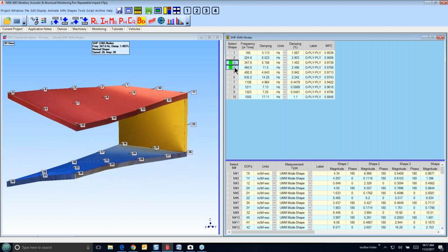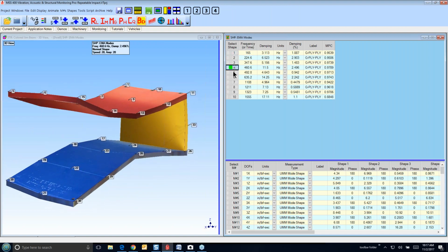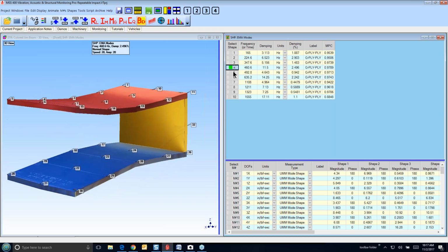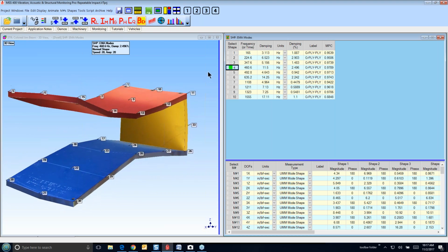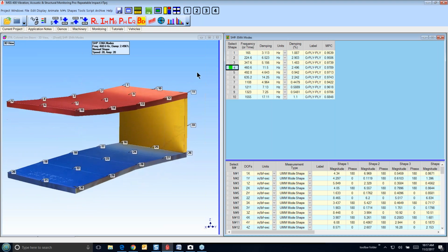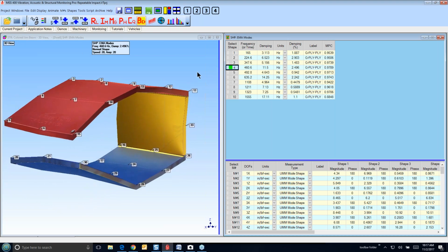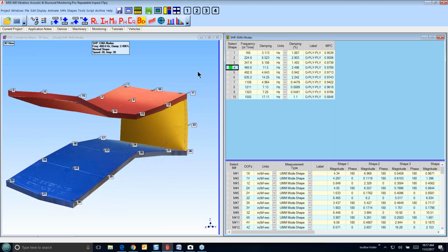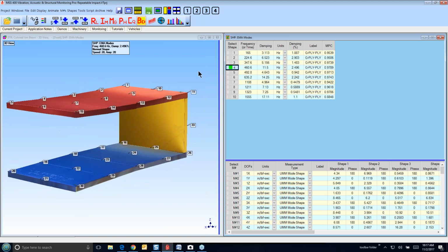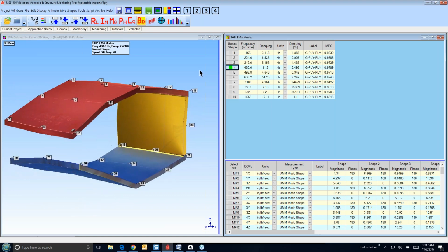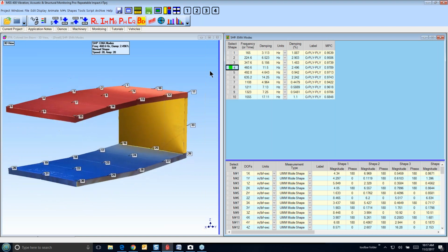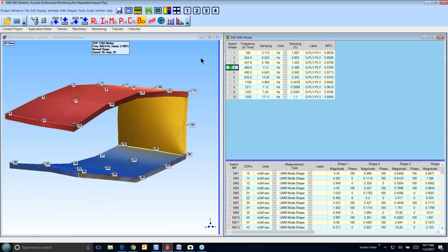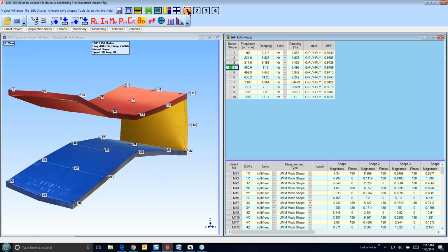So we can see when SDI values are high, that means that for a particular measurement, maybe the mode shape components for the two different points where I impacted are essentially the same. So again, the ODS correlation is going to give me a strong correlation between the current and the baseline as a function of frequency. Let me go back and hit the